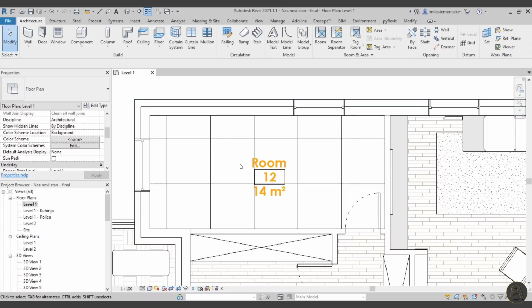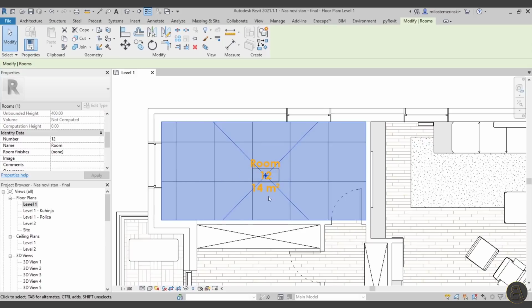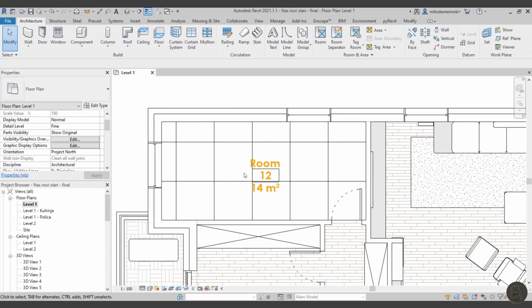So from there, we can judge that we need 15 panels. And if you're doing a small calculation like I am over here, this is probably going to do the job for you. So even though here the report said we need 14 square meters, or even less, like 13.5 or 13.6, in reality we really need 15 of these panels.